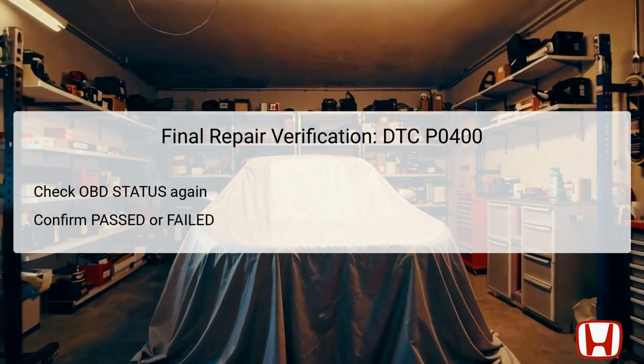In cases where the status shows not completed, you must ensure that all test conditions were strictly met and repeat the verification process accordingly. Effective final repair verification is vital to ensure that all components within the EGR system operate as intended and that the vehicle's emissions levels are within acceptable limits.